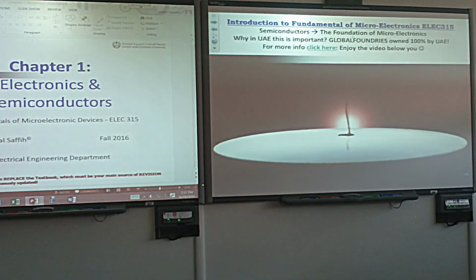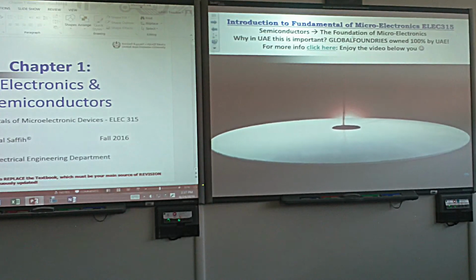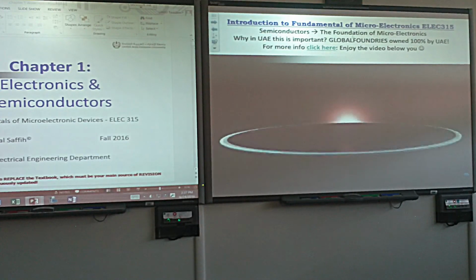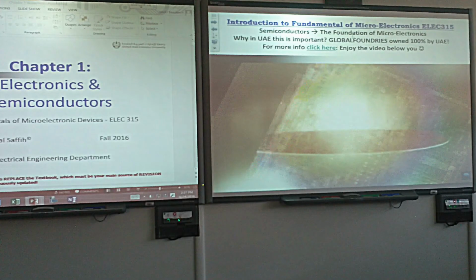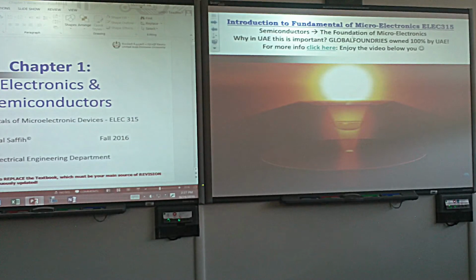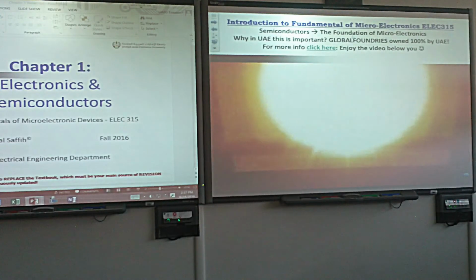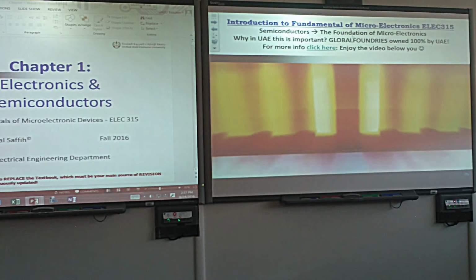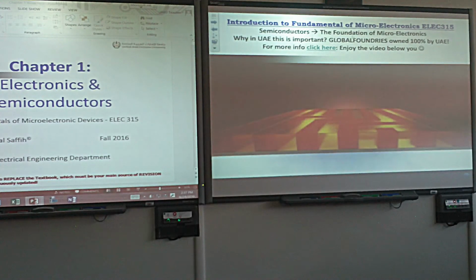The silicon disc is spin-coated with a photosensitive resist. UV light transfers the circuit structures depicted on a mask to the wafer. So the mask is like a film that has the circuit picture. The exposed parts of the resist are soluble and are removed by the developer.